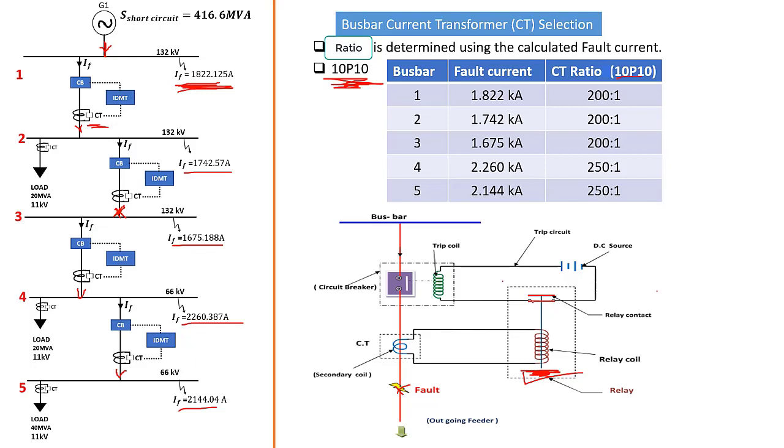So now the relay is going to trigger and the contact will pull, and that's going to close this circuit here. Once the circuit closes, you now have this DC source that's already ready here. That's now going to flow like this. Now that's going to create a current that's going to flow on the coil and energize that coil again, and the coil will now trip the release mechanism of the circuit breaker. So that's basically how this entire system works.